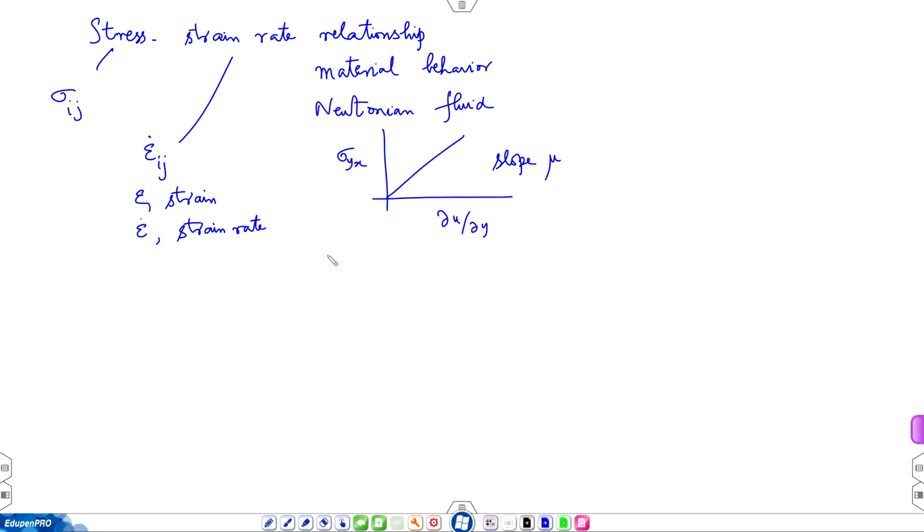Now, you may remember elongational strain from your previous courses. So, what is elongational strain? You take a small element of the material and pull it, and then its length changes from L to L plus delta L. So, delta L divided by original length is the elongational strain of that element, and it is connected to the stresses you have applied. Higher the stress, greater is the elongation.